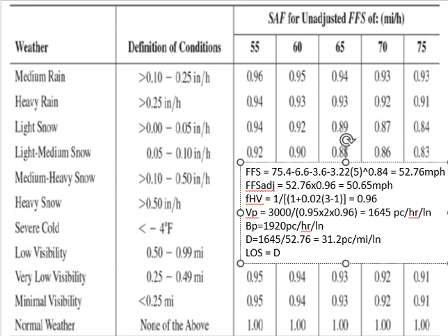This is the equation in front of you for the heavy vehicle adjustment factor. 2% was the trucks, and EHV was the equivalency factor of the truck. Do you see anything related to weather here? Any adjustment factor here? No. So move on. The next thing we calculated was BP, the flow rate. Do you see any adjustment factor there? We did not miss anything, right?